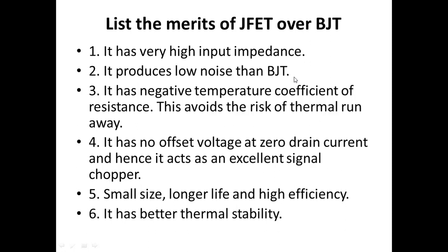And it has a negative temperature coefficient of resistance. This avoids the risk of thermal runaway. In BJT, we've seen that thermal runaway takes place. As the temperature increases, ICBO increases, IC increases, temperature rises, and ICBO increases further.